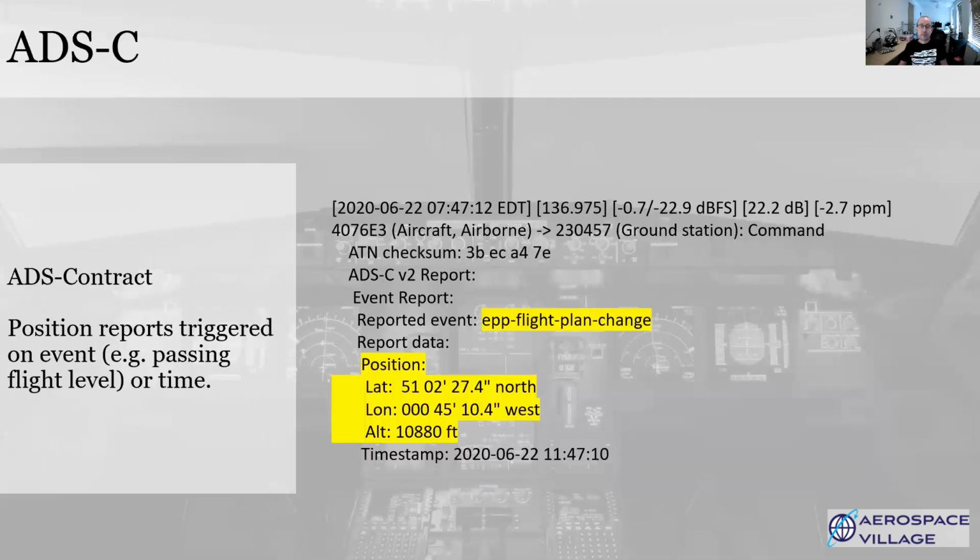You might be familiar with ADS-B, which is the position notification signal sent out on 1090 megahertz, which contains GPS position and altitude. And this is picked up by services like Flightradar24 and ADS-B Exchange. These are periodically sent out by the aircraft when it's illuminated by primary radar. But for FANS, we need more granularity and information, so ADS-C is used instead.